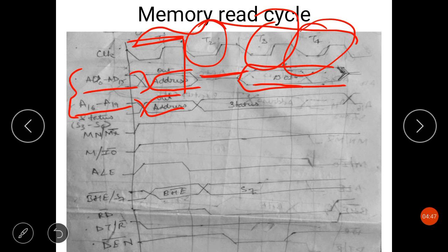However, if the 8086 ready input is still low at the end of a wait state, then the 8086 microprocessor will insert another wait state. The 8086 microprocessor will keep on inserting wait states until the ready input is made high again.